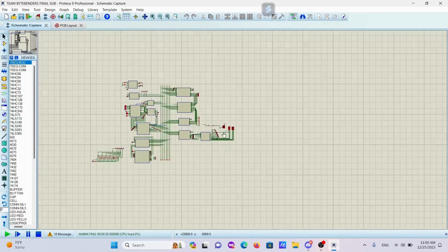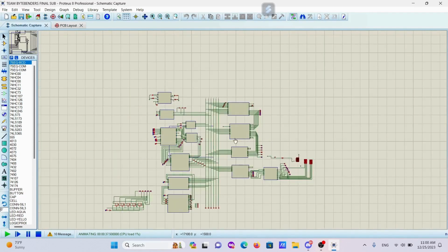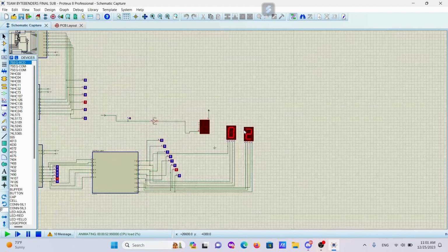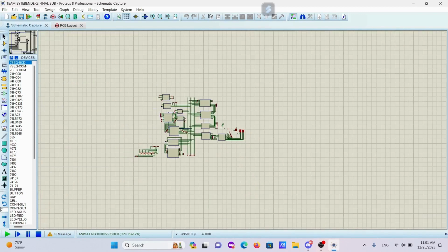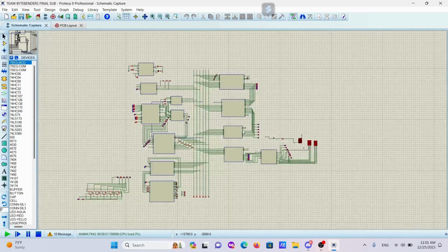The result is right. So after doing the addition and subtraction operations, we can see that our program is running successfully. We can do the addition and subtraction programs successfully. When we subtract a larger number from a smaller number, then the sign comes out minus, and when we subtract a smaller number from a larger number, then the sign bit is 0 actually, so we cannot see any sign here. So we can see that our program is correct.